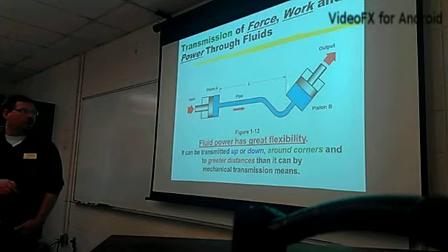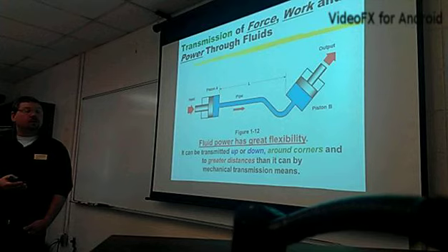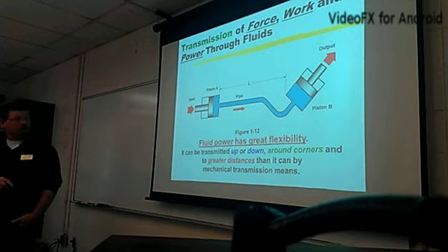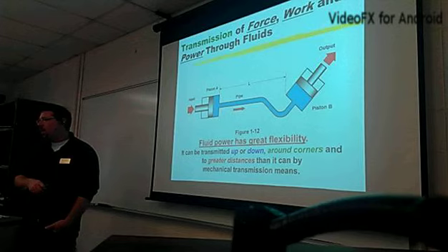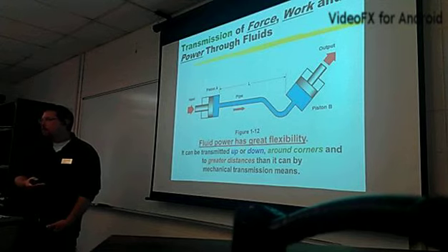And there's really the only things that are going to go wrong on an actuator is either you're going to break it because you did something wrong or something went bad, or you're going to get a leak. You're going to blow a seal. That's about it. Very rarely do they actually physically wear out because they're always lubricated. So the seals wear out before the metal does.